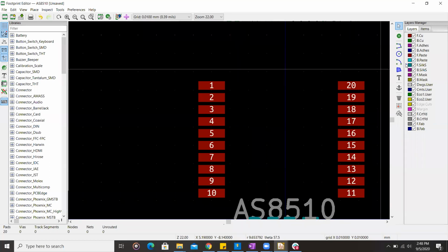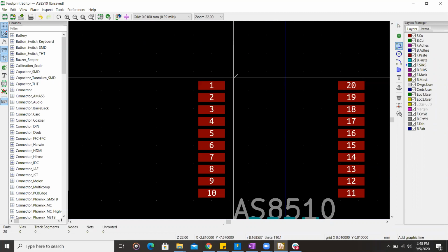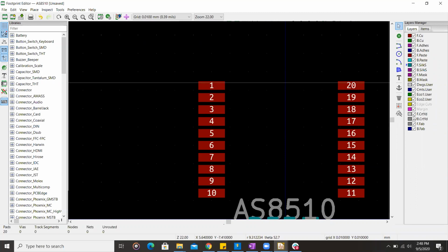Okay, so what you want to do is use a silkscreen layer to do that. And the silkscreen layer, remember from the earlier tutorial, actually does get printed on the PCB, but the courtyard and fabrication layer do not. So I'm going to describe what the courtyard and fabrication layer actually mean. So the courtyard layer, it's the keep out area for other parts to follow during assembly.